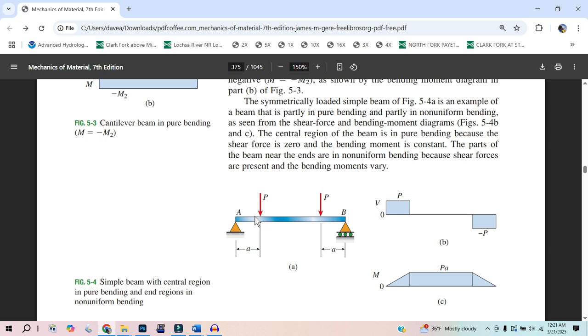These I-beams, that's the other thing, that actually gets hella overlooked. And this is from first chapter stuff. If I have a 1-inch bar of steel, like a 1-inch cross-section that's kind of long, I can hang a semi from it. Not a full one. But it's got 58,000 pounds. A full semi would be 80,000. That's a good reference. So for sure a half a semi, or like an empty semi, you could hang the semi truck and trailer empty from a 1-inch chunk of steel and be very happy about it. Materials are strong. Cool.